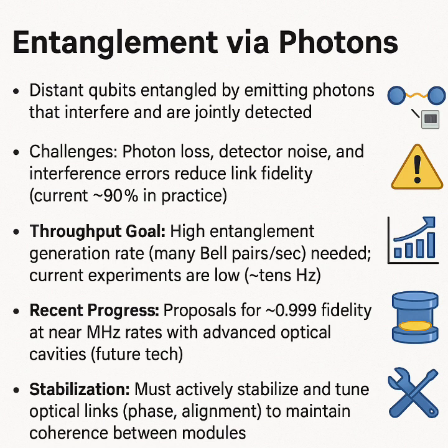Merope Quantum's perspective: photonic interconnects present dynamic problems. Unlike static qubits in a single device, these links involve flying qubits, photons, and lots of analog components, fibers, beam splitters, detectors, that can fluctuate. Merope Quantum's strategy, as we will see, is to incorporate real-time telemetry and control to adapt to these fluctuations. For example, if a link's loss starts increasing or an alignment drifts, the system should notice immediately via sensors and error rates and adjust, maybe by retuning a phase shifter or increasing laser power, etc., on the fly.